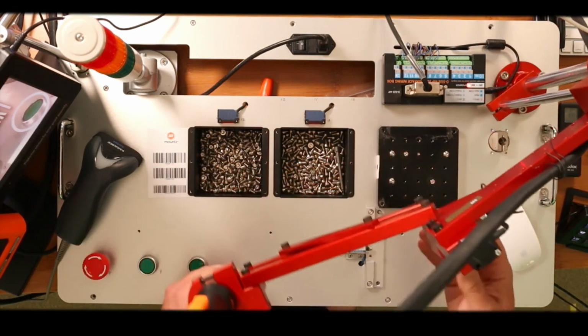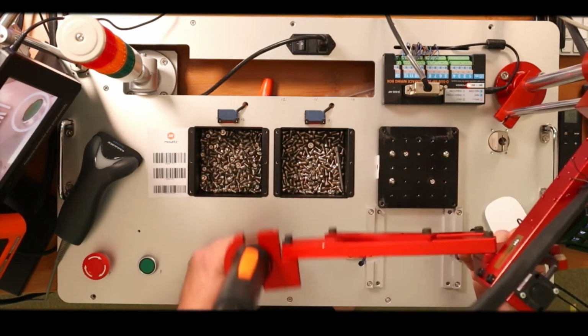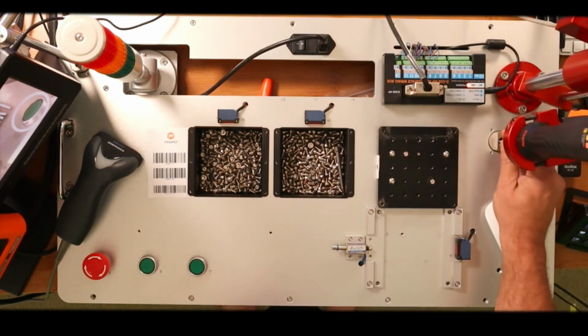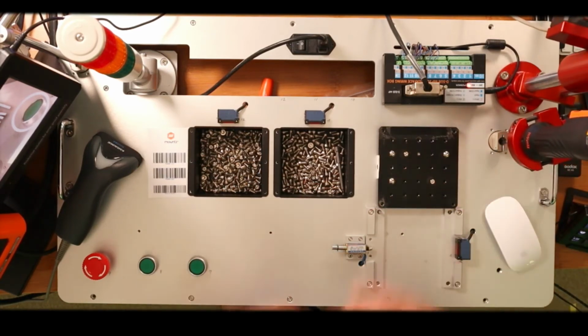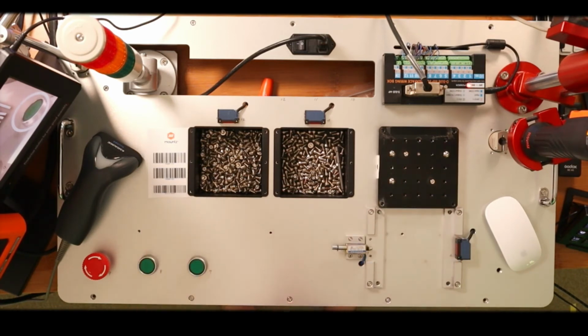And the way that this works is that we have encoders that will monitor where the tool is in space. And this helps to actually guide the operator to a specific part, a specific assembly that they would be doing. And it only provides power to the tool when the operator is in the right place. And not only does it provide power, but it will also provide the correct preset that needs to be used, and it'll help walk the operator through the assembly.